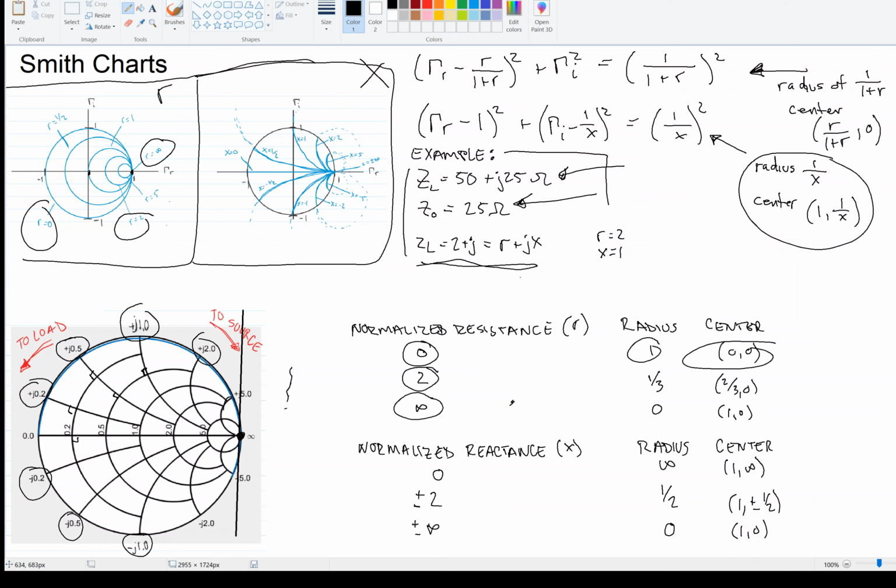Usually on these Smith charts, clockwise represents moving towards the source, and counterclockwise is towards the load. So if you know the input impedance somewhere on the line and you want to go down the line towards the source, you can figure out how much you need to rotate to your new point to find the new input impedance. Again, lambda over 2 corresponds to 360 degrees.